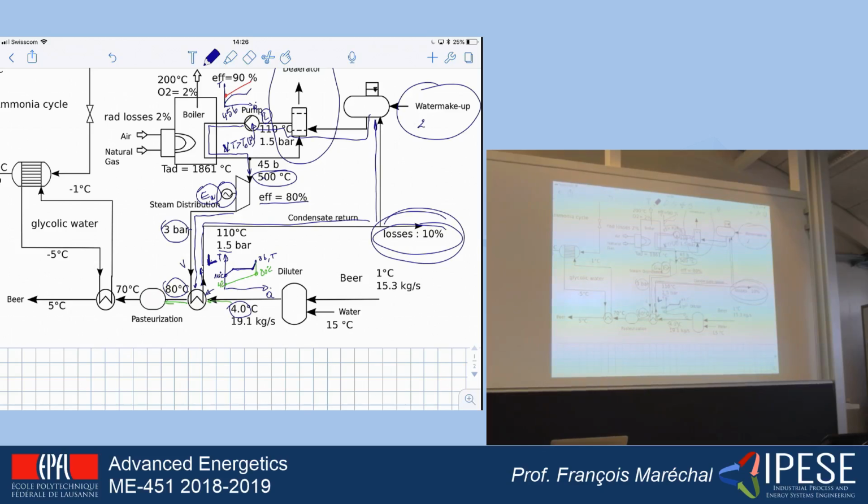So at 25 degrees C. Right? So this is the water that is entering, fresh water that is entering the cycle. And this fresh water is at ambient conditions and has been demineralized by using membranes, for example, to take out all the minerals, because I don't want to have minerals accumulating in this cycle here. Okay? So now what is happening is that I'm mixing water, which is at 110 degrees C here, with water at 25. It results in a certain temperature here.